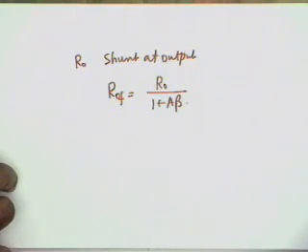So all these results only hold for negative feedback. Yes, so positive feedback just changes the sign. Minus. That's right. In positive feedback, but make sure that A beta is less than 1. A beta is never allowed to exceed unity. If it is allowed to exceed unity, then the whole amplifier falls to the ground. It can be junked.